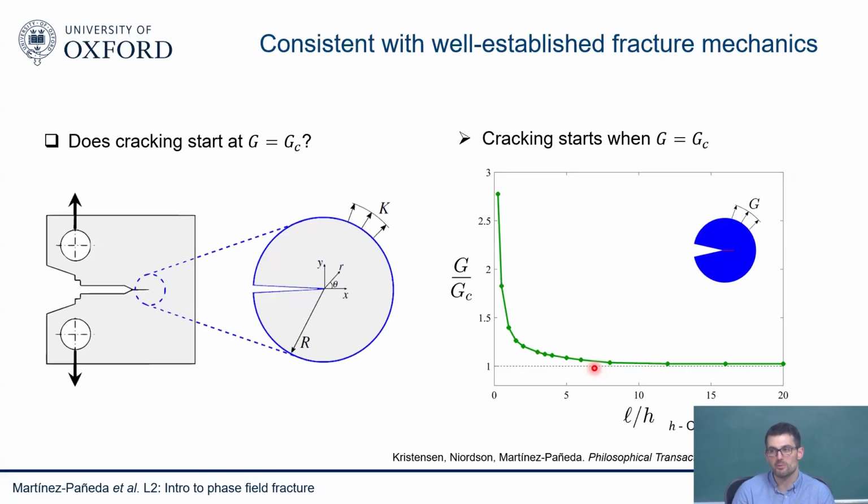In the first papers of mine and so on, people were taking 2 times, which is somewhere here. It's not too bad, but I will feel a bit safer at 5 times. You still see a lot of people in the community taking an element that is half the length scale based on those early papers, but based on this type of results, I'll feel more comfortable with 5 times. And for your analysis, you are actually computing L from the previous formula that you saw, the expression between.